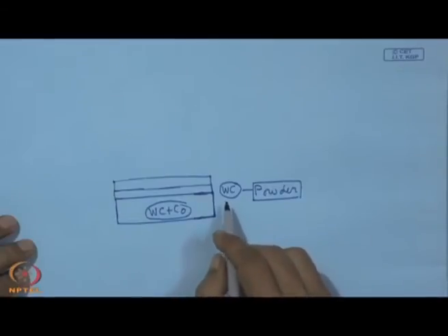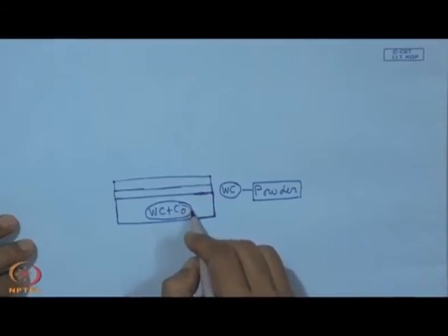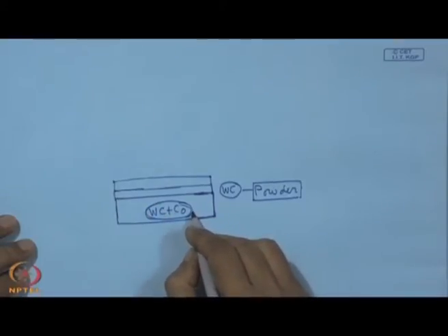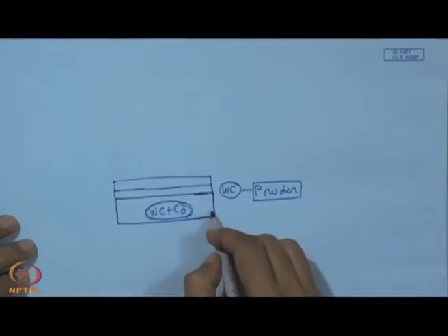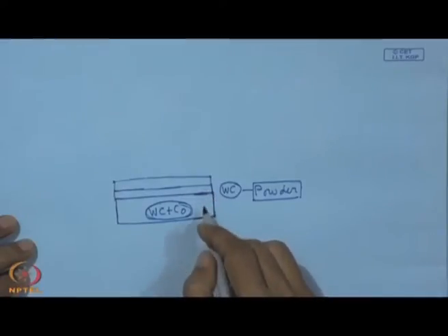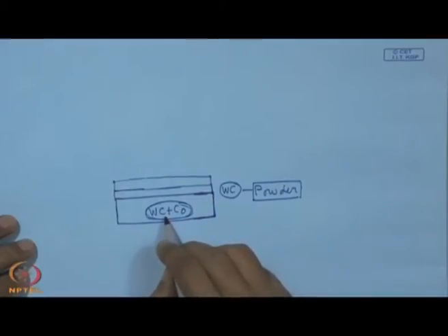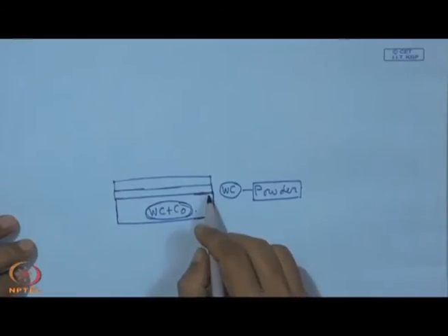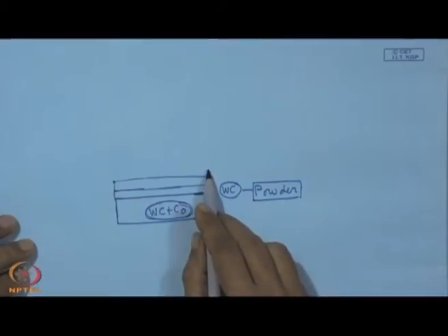So, this way we can also see that the detrimental effect of cobalt can be eliminated, and we can have a fairly fine transition between tungsten carbide cobalt, tungsten carbide, and also tungsten carbide diamond, and tungsten carbide diamond to pure diamond.